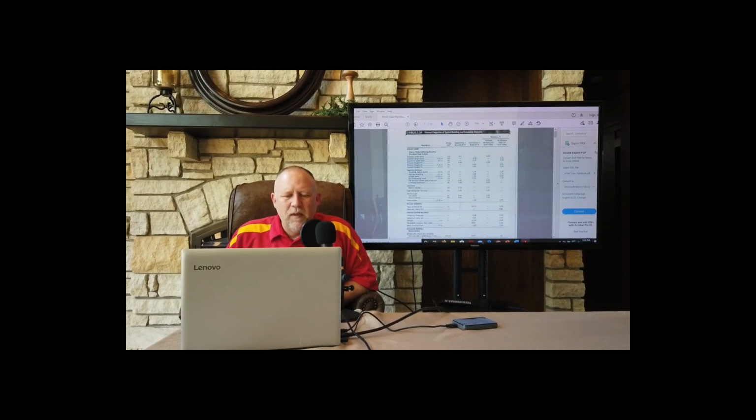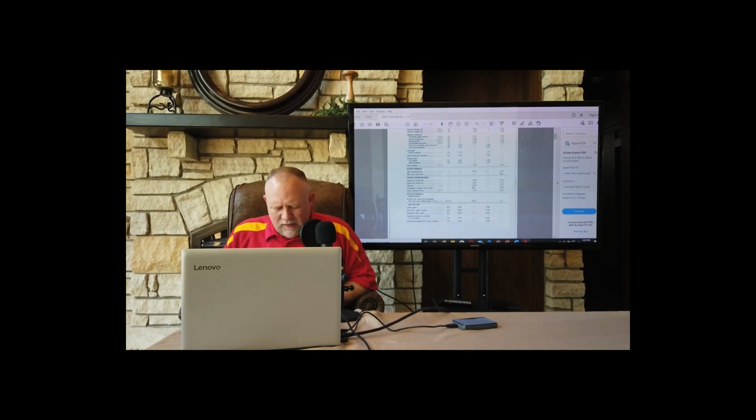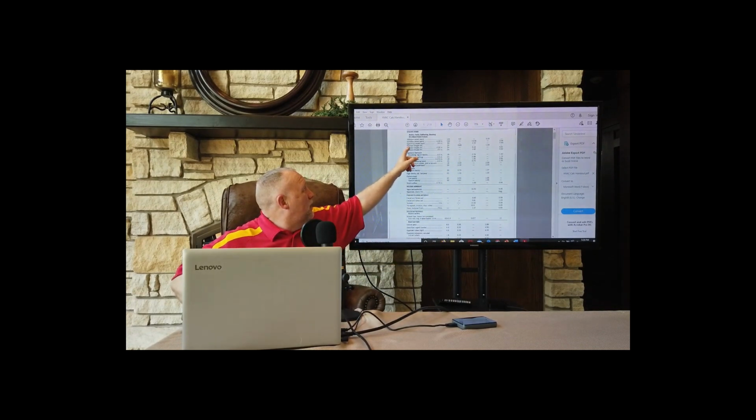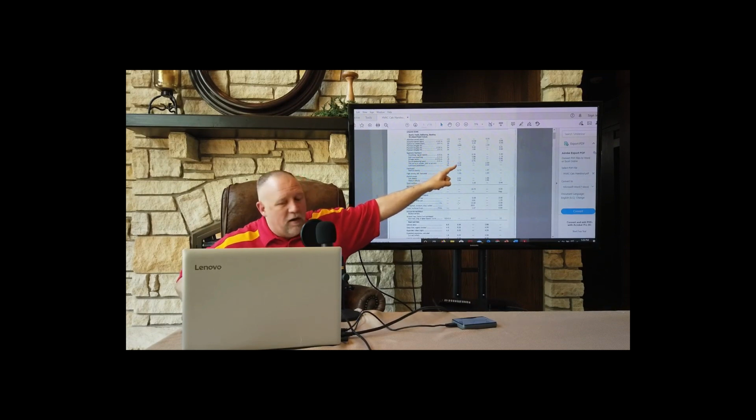All right. So some of the more important ones that we're going to need in here. If I say batt insulation, go down to where it says building boards. Let's start there. That's where we find gypsum or plasterboard, right? Let's see here. Right here, 1/2 inch. So it lists it as a 1/2 inch gyp board. So the R value is over there on the right.